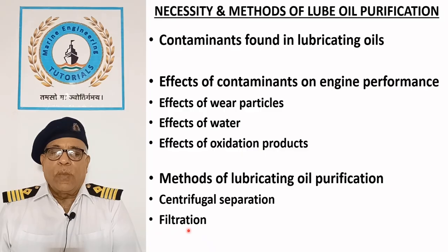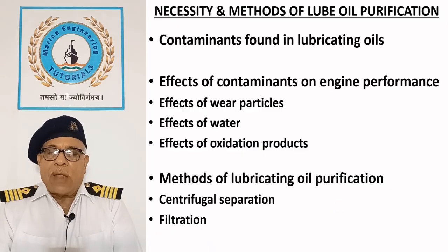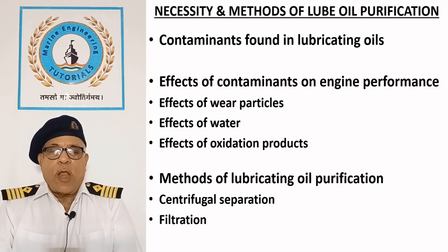Filtration. Filtration is the last stage of lubricating oil purification before admitting to the engine. Both magnetic and fine filters are used to trap ferrous and fine particles, as small as 5 to 10 microns with fine filters.